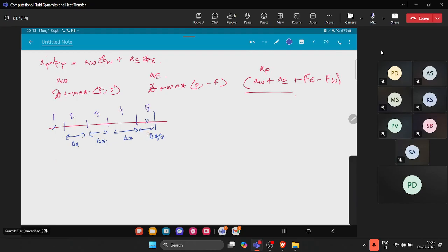As of now, let's ignore these. We actually have 5 control volumes over the whole domain. 2, 3, and 4 are your internal cell centers. As derived earlier, we find the equation for the internal cell centroids, and then go to the boundary cells one by one and create a matrix of our own, which we can solve by putting in the values of D and F, and then get the temperature profile over the whole room.